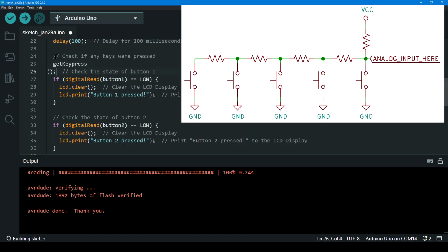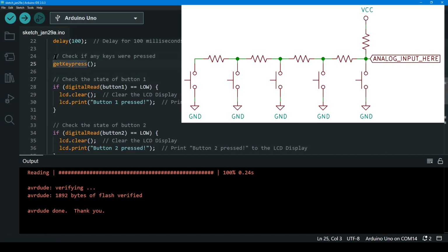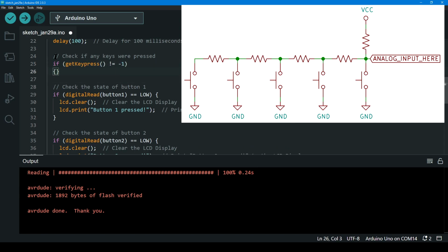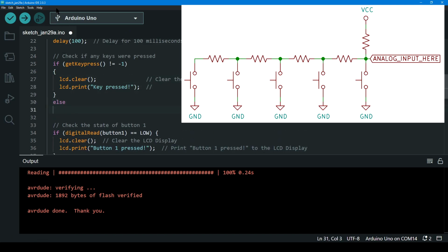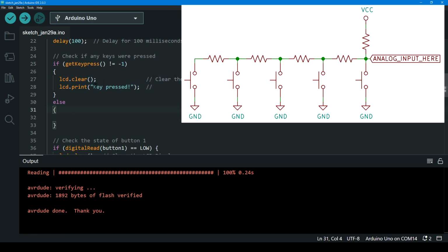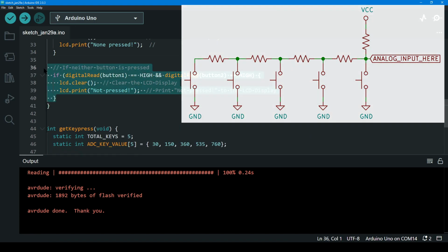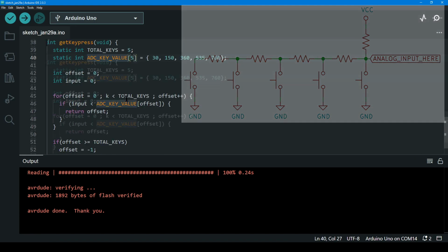The display board does this differently. Each tactile switch is part of a voltage dividing structure. Assuming that only one key is pressed at a time, this resistor network is going to generate a slightly different voltage depending on the key pressed, and we can read that voltage using one of the analog inputs. OSEP likely did that so that the entire key array can be read using only a single pin.